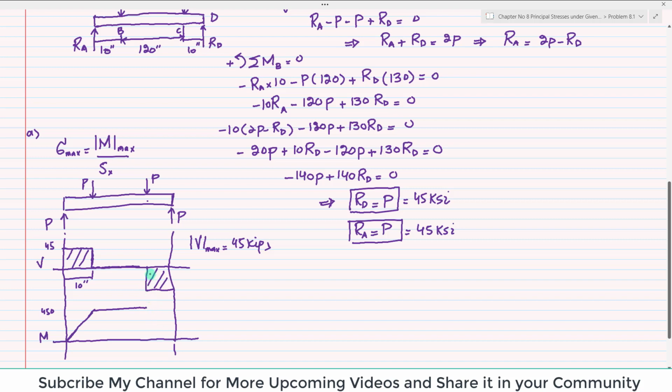Because this line is negative, minus 45, and the bending moment will be decreasing. Here it comes to this point. So this is the bending moment diagram. From here you can find that the maximum bending moment is 450 kips-inch.